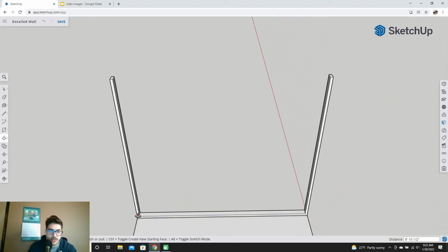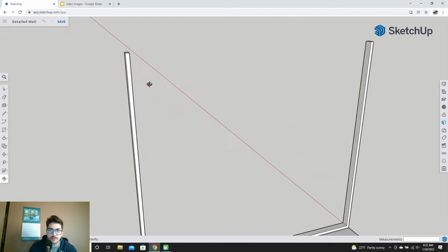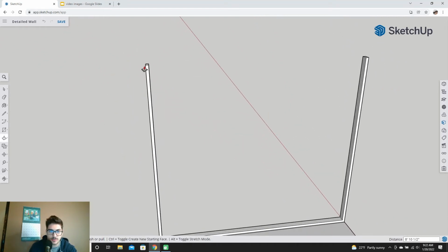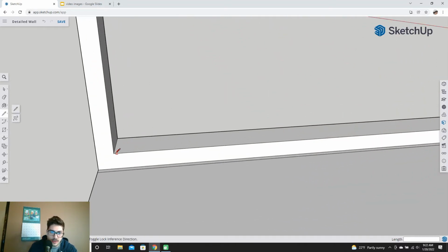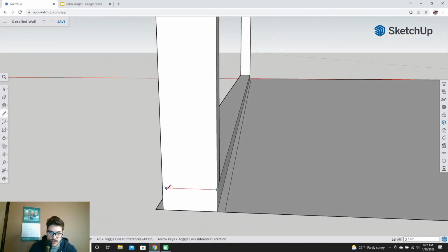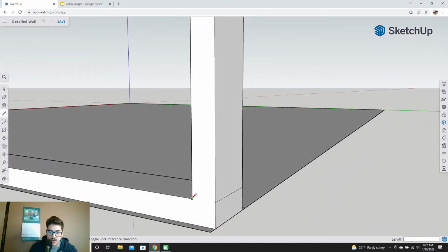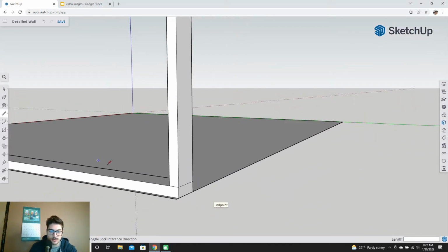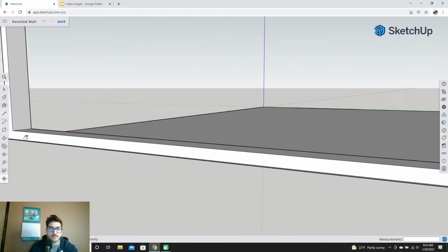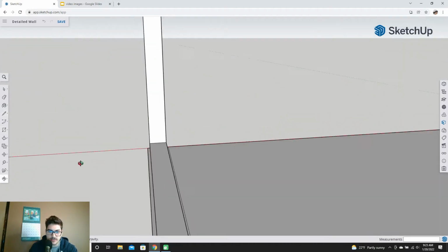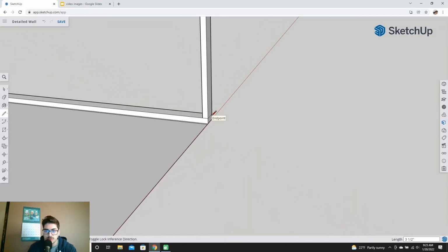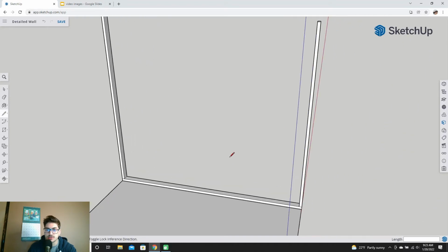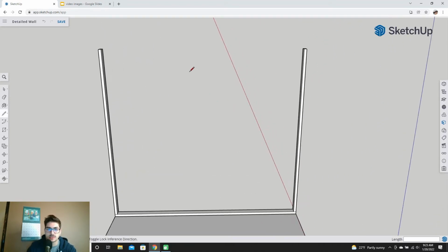So you grab your extrude tool again, you pull them up to the 9 feet, which is where making those 9-foot high lines is really nice because we have a finish point to extrude them up to. And just a little cleanup thing as you're going, you probably will want to go to where you extruded and draw horizontal lines across your model. Especially if you're trying to show individual studs where they'll start, where they'll end, because a lot of times you can use a model like this for determining how much total material you have to go and get. So that's just my spiel there. But yeah, so now we have the outer two studs, and that looks pretty good.